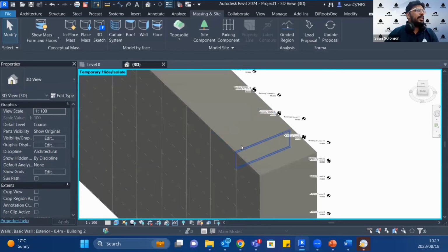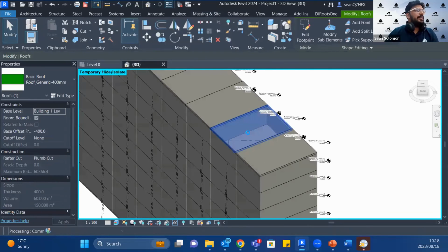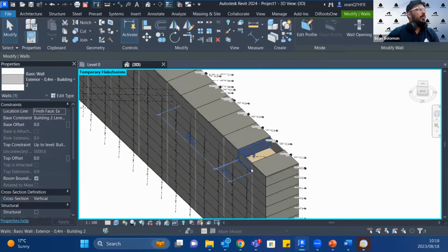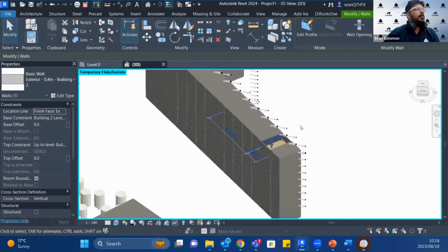We can see how it actually split up this line building for us. I'm just going to hide this. We can see it created these internal walls to divide the different units and so on. So quite nice. Now, the next step would be if we were to maybe add in some buildings from another proposal that we want to reuse here, or we want to start to model something in Revit, we can do that and push it back into Forma and see that reflect. So here's these internal walls that it added in for us as well.